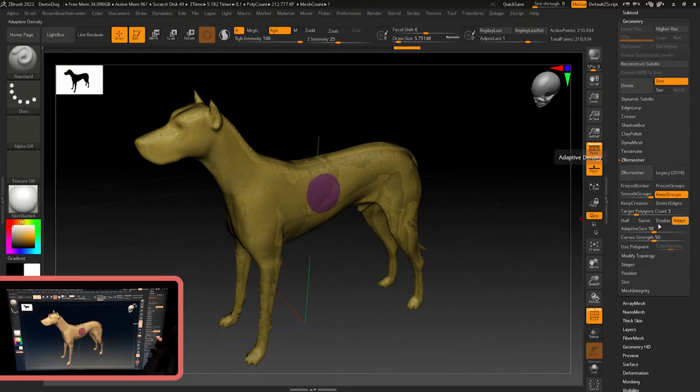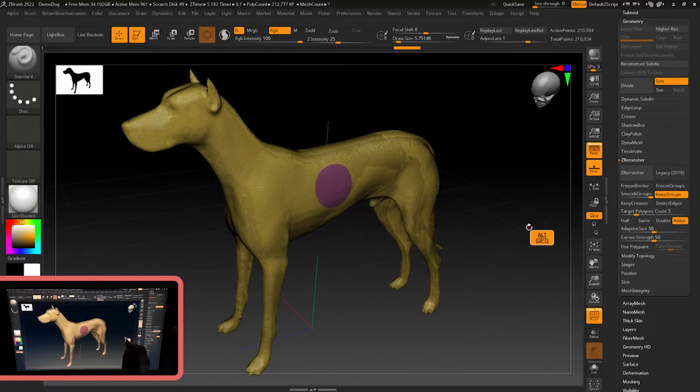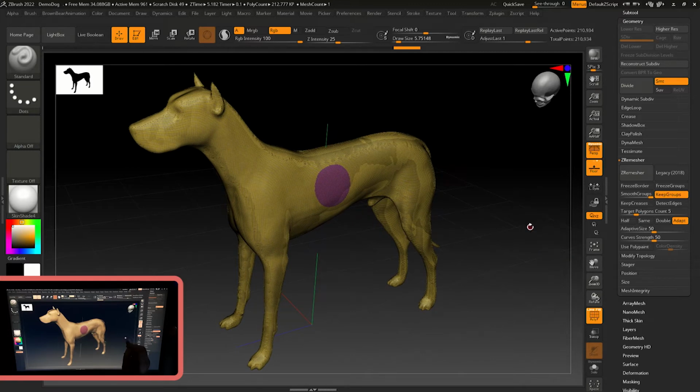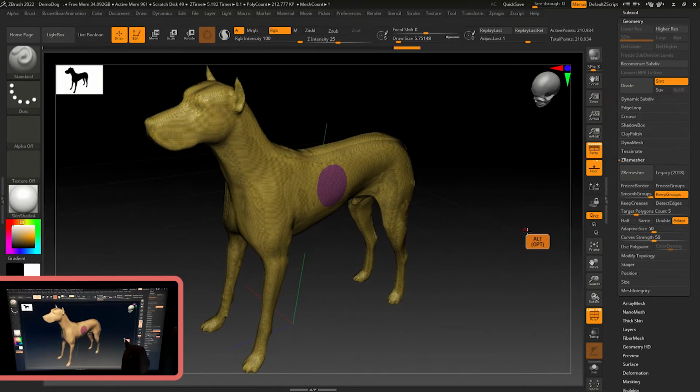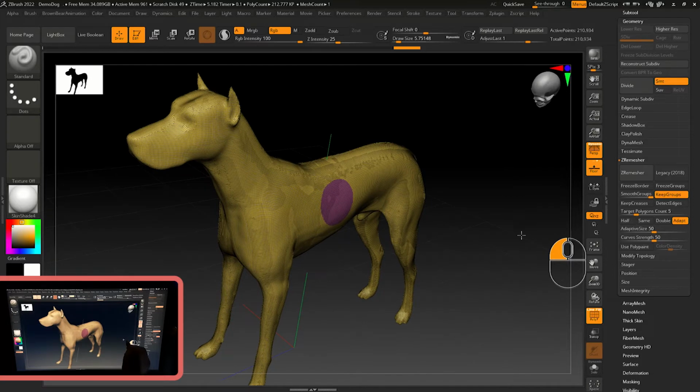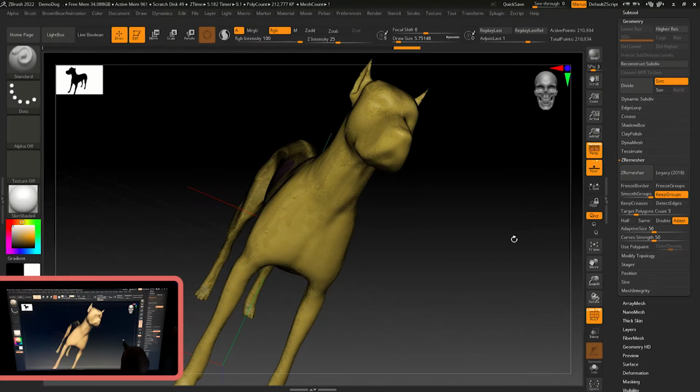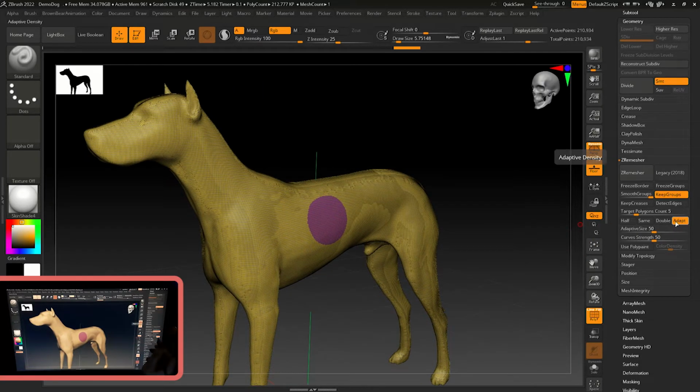And adapt is useful in many ways, but I don't like it that much. It's helpful if you are just playing with zero mesh and zero mesher is helping you in different ways. When you press adapt, it will work according to both the adaptive size and the target polygon count. But if you press adapt and you have a higher adaptive size, it won't look at the exact polygon target.